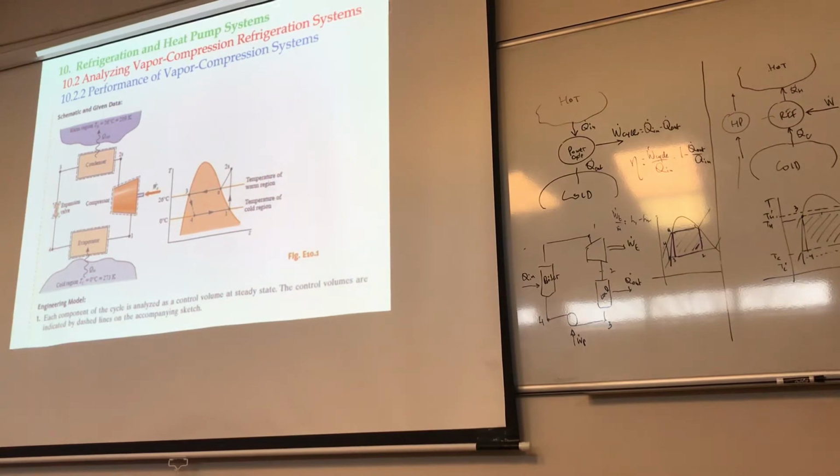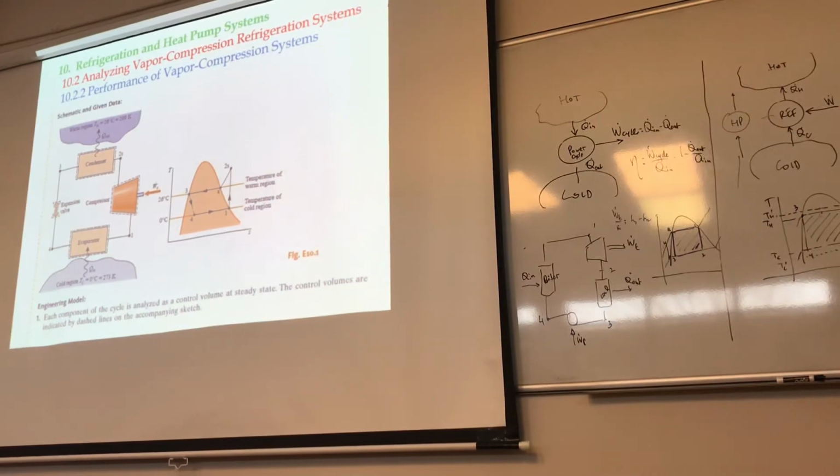Now you know that pressure, so that means state 2 is well defined because we know its pressure and its entropy. Now, how am I going to find what is the H? I know that state number 2 now is in superheated, so I need to move on to the next table, right? Instead of being at A11, I need to go to A12. And when you go to A12, what you are searching for is the state that has that pressure that you just got.